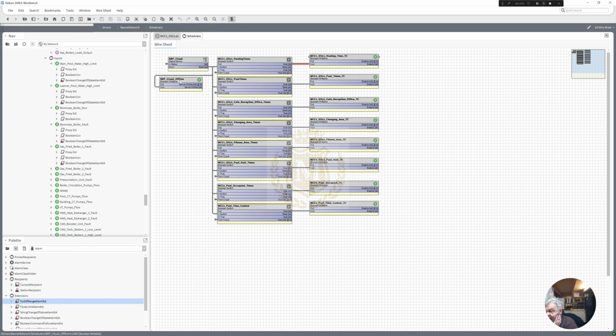The reason I do this here as well, this Boolean, is that it gets sent via BACnet to the controller, and the person who's writing the logic knows that when the server is online we can use the time clocks there, and when it goes offline, he knows he's got to use the time clocks that are in the station.